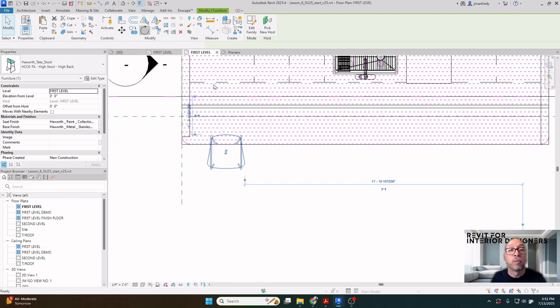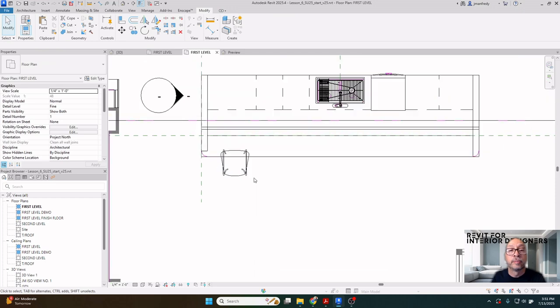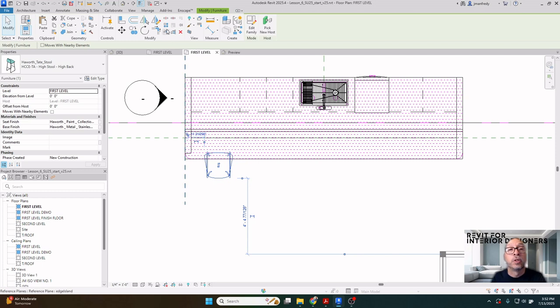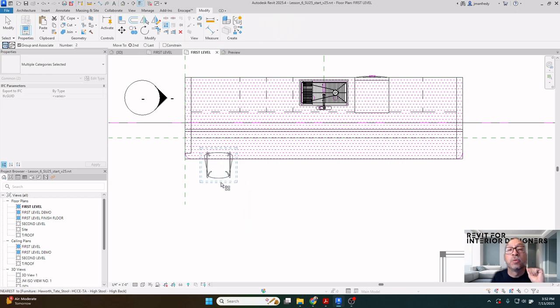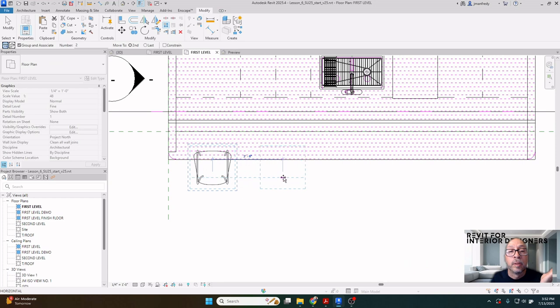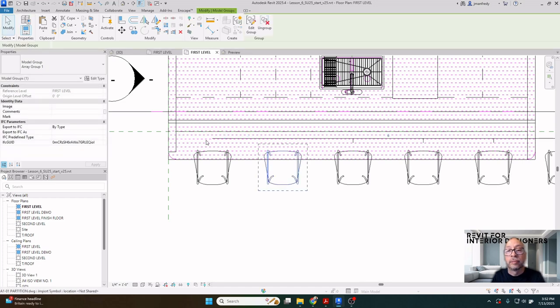I know this chair is flipped over backwards. I'm going to rotate it 180 degrees. And I've got that chair in position. And I want that chair copied 6 times. I click on the one chair and I use the array command. With this command, I can click on array and I can choose the second location of the chair. So here I'll grab its center and I'll drag it over to the right slightly and I'll pick a distance. Let's say, what have you, 3 feet, for example. And here it lets me highlight this number and choose the total number of chairs that will be this distance apart, 6, enter.